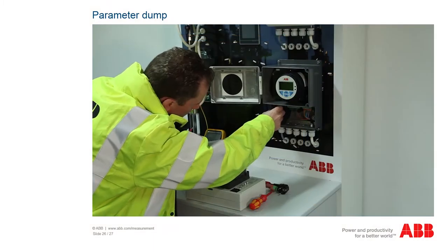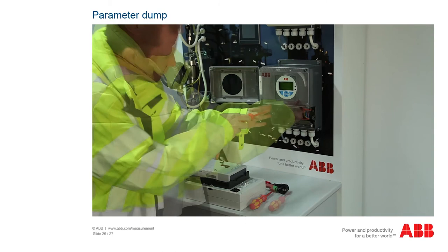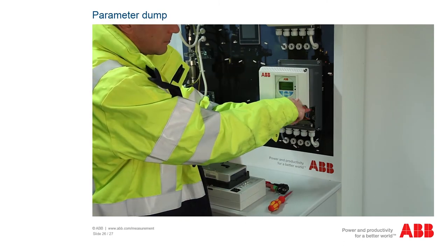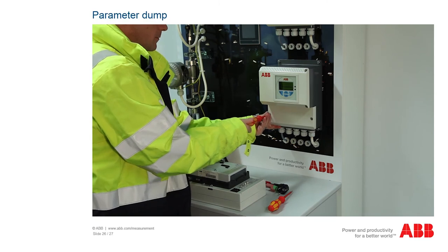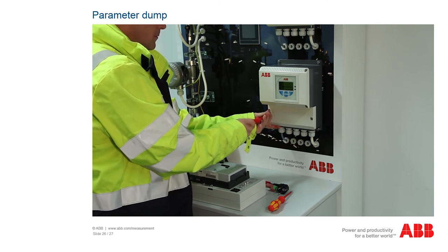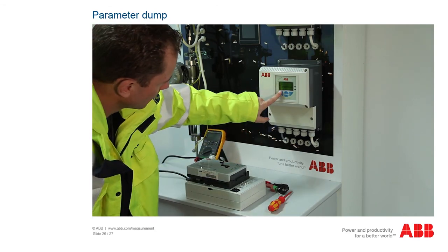Check the cabling again, reinsert the control unit fuse, and screw the control unit closed. Finally, reinsert the sensor PCB. To do this, carefully reattach the connectors of the coil and electrodes. Insert the PCB and screw it down. Close the sensor housing.